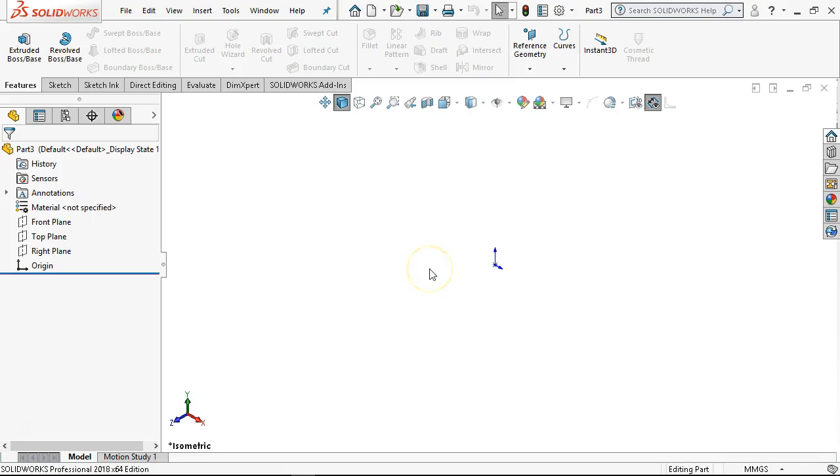Where we have to make these decisions is I get a drawing from a vendor, and maybe it's a PDF, and I want to get as much of the geometry, but I don't need all of the geometry. I just need the envelope. I don't care about internals. And if it's not a rotating mass, I'm not really concerned about balance. Just I need it to fit into my assembly somewhere. I'm still kind of guessing at what their design intent is. I know what mine is, and I'm relying on their geometry coming in. And until I have the part in my hand and I'm looking at it and saying, yeah, that matches the drawing, I'm not really comfortable.